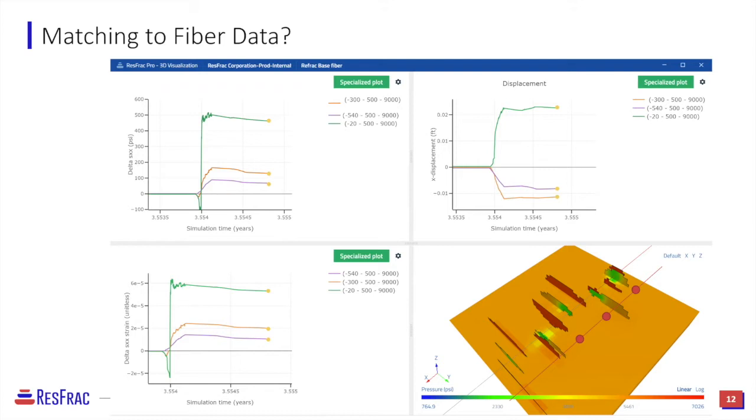It may be that that is like a 30-foot separation. And so when you look at fiber responses, you see an interesting phenomenon where if the fracture is located between the 2 points where you're taking the difference of the displacements, the fracture is opening outwards. And so one point will be going left and the other is going right. And so you actually see the 2 points pushing apart, like in tension. And then once the 2 points are all on one side or the other of the fracture, now they're both pushing in the same direction and you see compression. So it's sort of interesting in the fiber responses that you see this band of tension that's created by the resolution of the fiber. And then outside of that band of tension is compression.